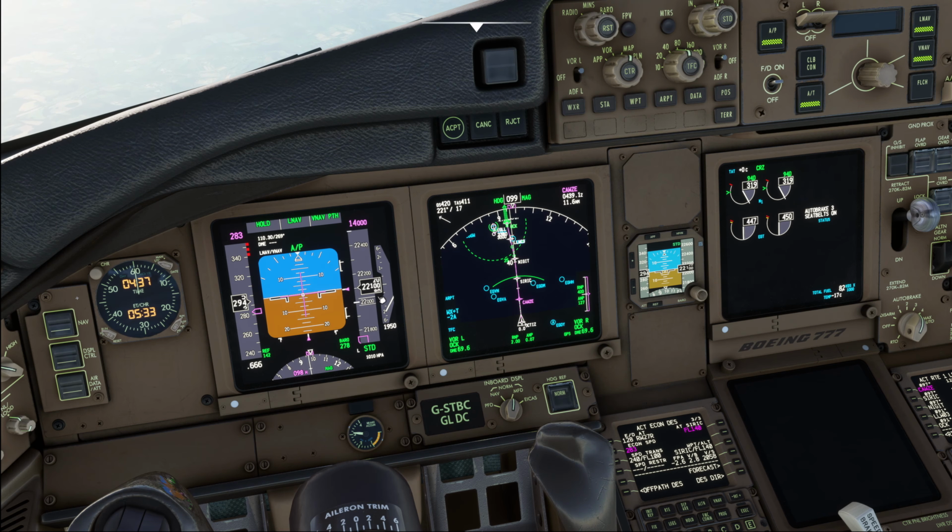So when we're passing 22,000, we should be about 24 miles from Zurich. Now, since we have a tailwind, we take a little bit longer distance, and in general, you can see that this cross-check works rather fine. We're around about at 30 miles over here, so tiny difference, but the general gross error check is correct.